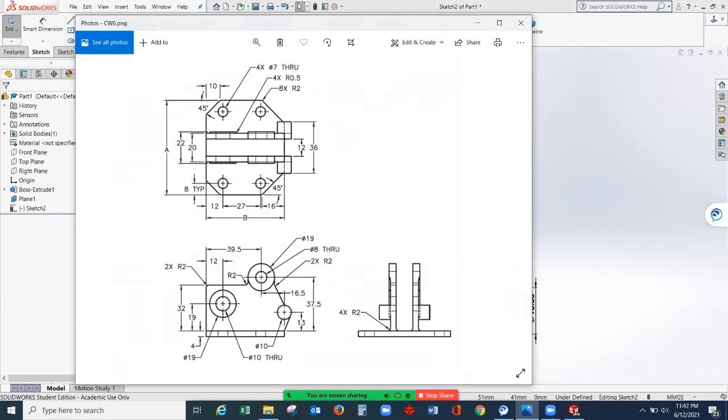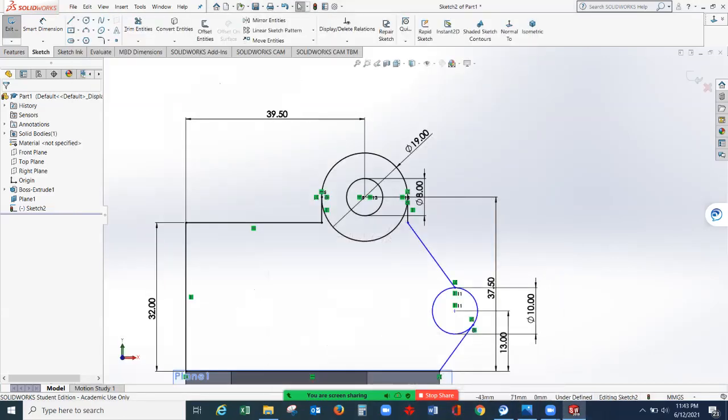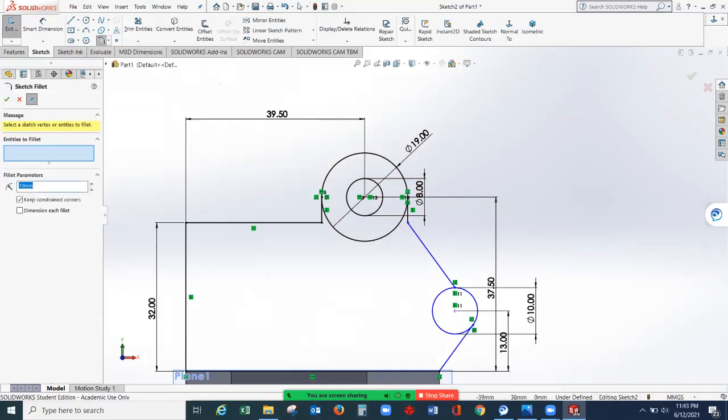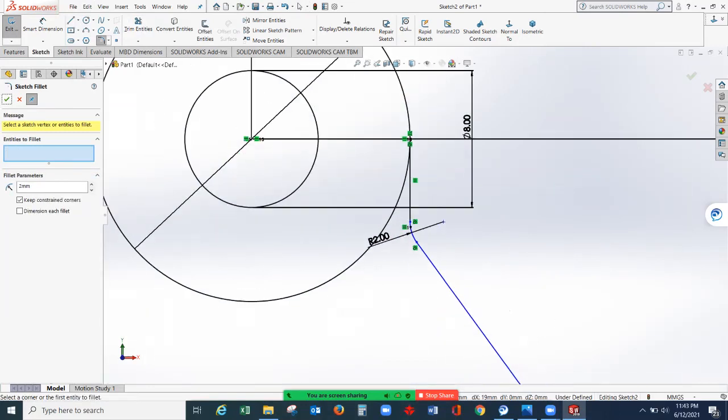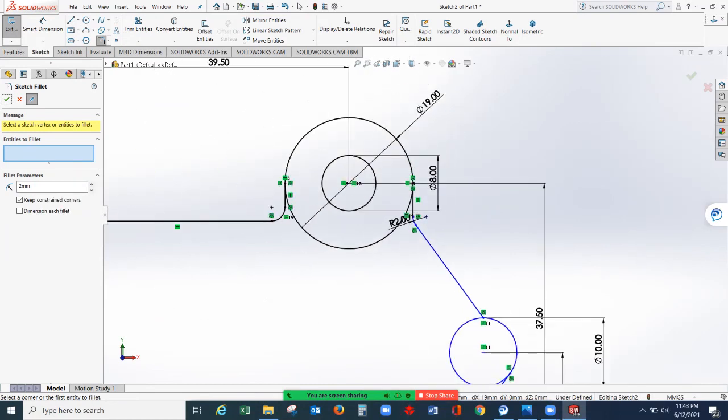That's it. So from here, you have a fillet radius of 2 from this point and at this point. So R2 means that's the radius of the fillet corner here. So 2 times means you have 2 drawings here. So 1 and 2. So from now, I'll create one fillet, which is having a radius of 2. So where's the fillet? So from here, sketch fillet. Type the 2 millimeters radius. Select this point and this point. Select this green check mark so you can get closer. It is filleted at this corner here.